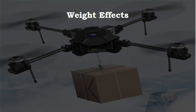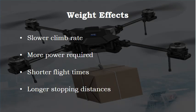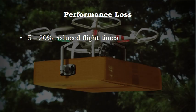The heavier the payload, the greater the effect it will have on drone performance. Issues that can be dealt with include a slower climb rate, more power required to generate lift, shorter flight time due to draining the battery quicker, and a longer stopping distance required when landing. The typical performance losses due to weight are a 5 to 20% reduced flight time due to a greater voltage pull on the battery.